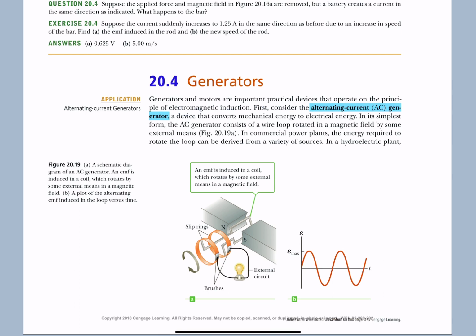But as the wires are moving in the magnetic field, it will create an oscillating current. And the more different magnets you have around an axis, the more peaks and valleys you're going to get. But the current is going to oscillate positive, negative, positive, negative. In North America, our generators operate at 60 times a second. The current oscillates 60 times, reverses direction 60 times each second.